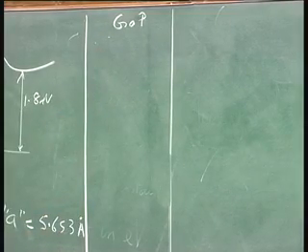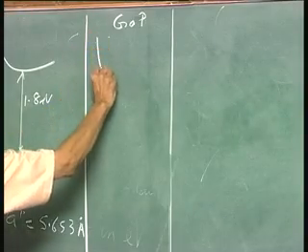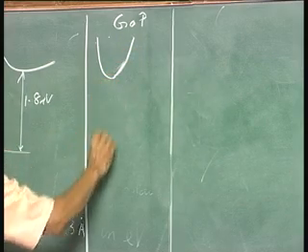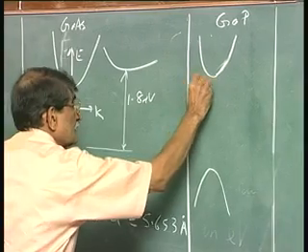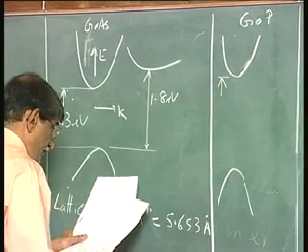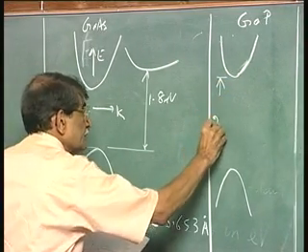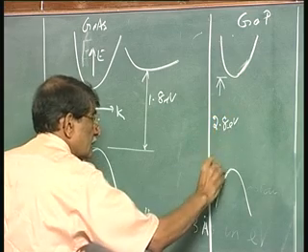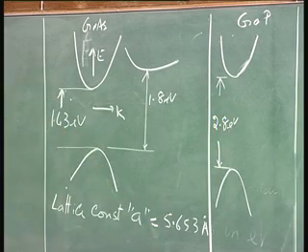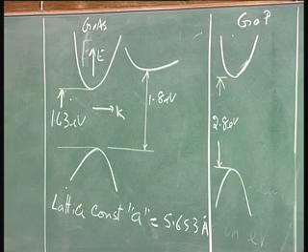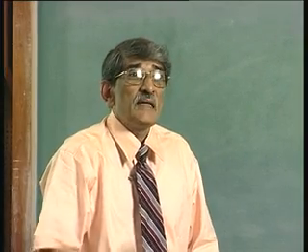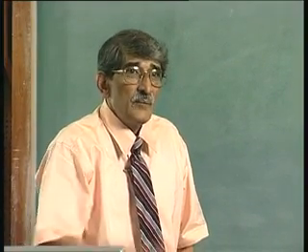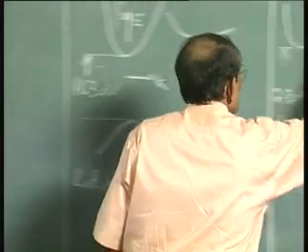So, see this here, you have gallium phosphide which is coming like that and something like this, and that is actually 2.8 electron volts. It is not a direct band gap semiconductor, it is an indirect band gap semiconductor, which would mean you will have a satellite valley which is below that. So, that is actually somewhere here.